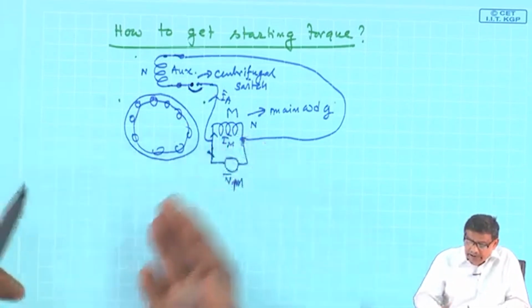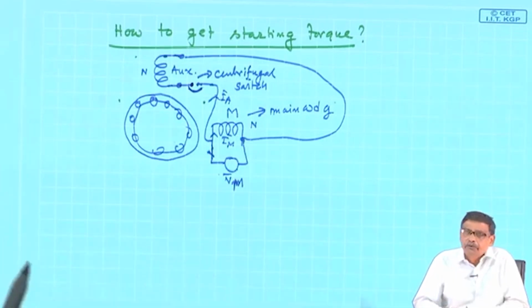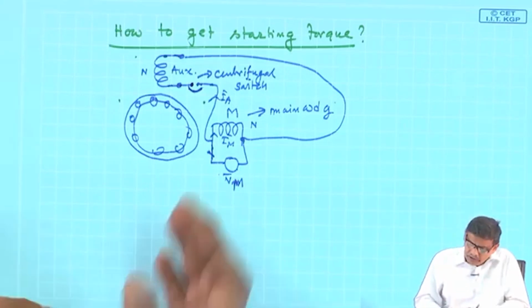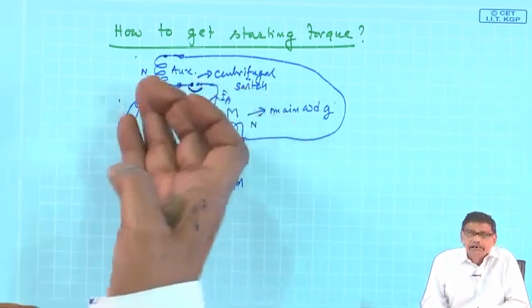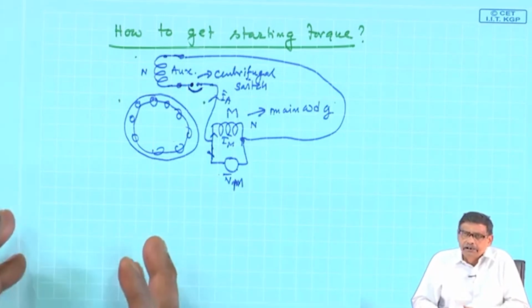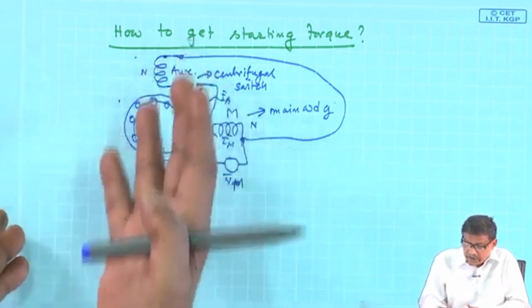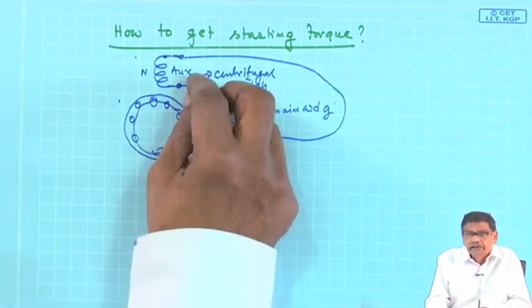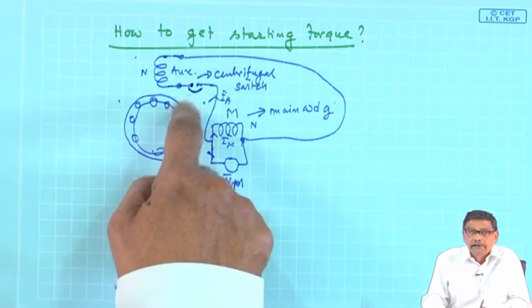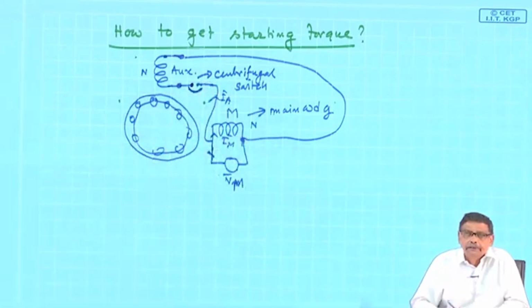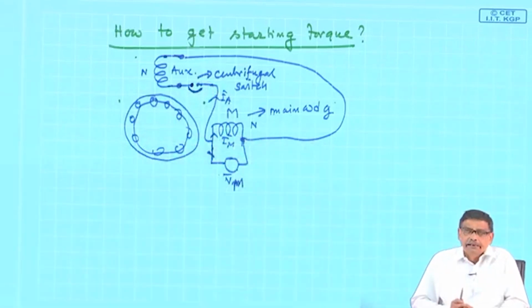So, primarily if it is really a single phase induction motor, ultimately it has to run on a single winding, and the auxiliary winding is brought in to assist the motor so that it can develop some starting torque. After it has developed starting torque, in presence of both main and auxiliary winding, the machine will accelerate. After it reaches some speed, this switch, which is speed dependent, will open circuit. It is normally a closed switch otherwise. So, that is the idea.